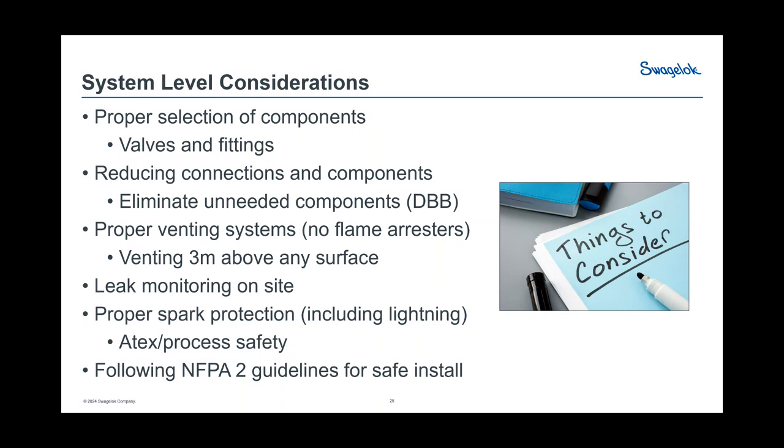So the lower flammability limit is 4%. The safety limit is 1%, and that's what it's used for, is calculating. The elimination of unnecessary components is really, really important. I'm talking about double block and bleeds in a second here, but one other thing is properly venting the systems.